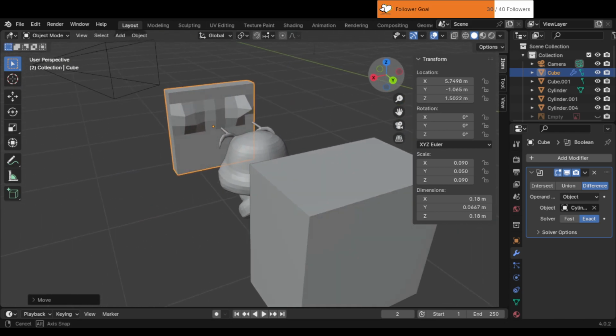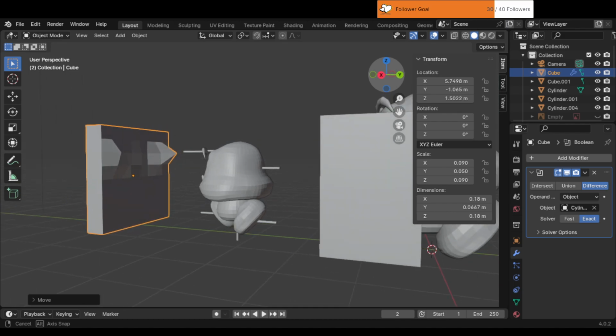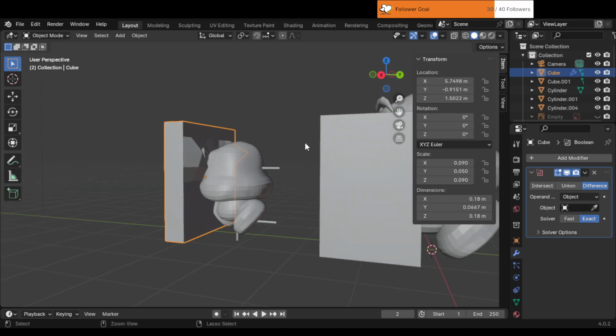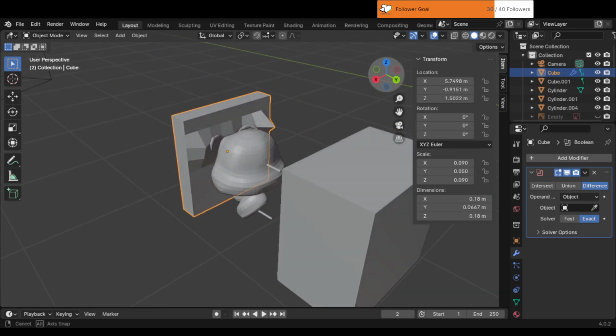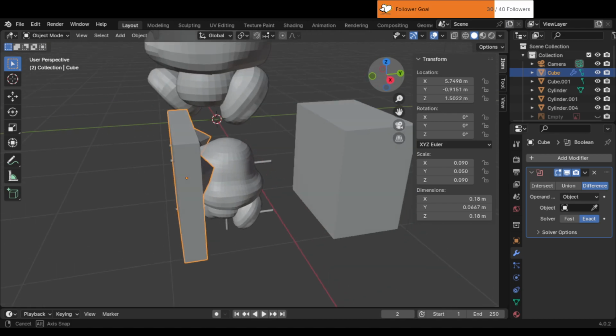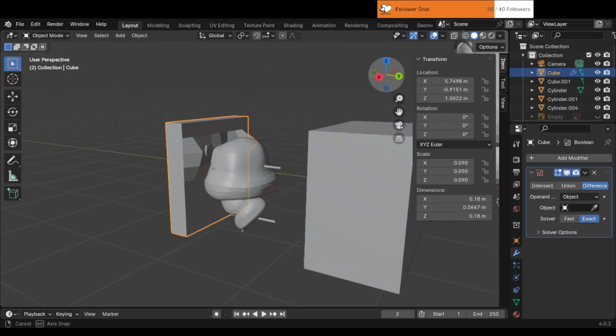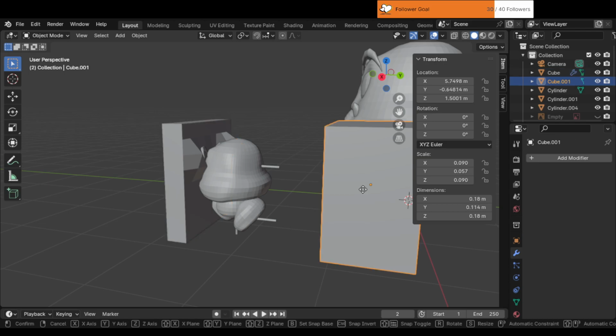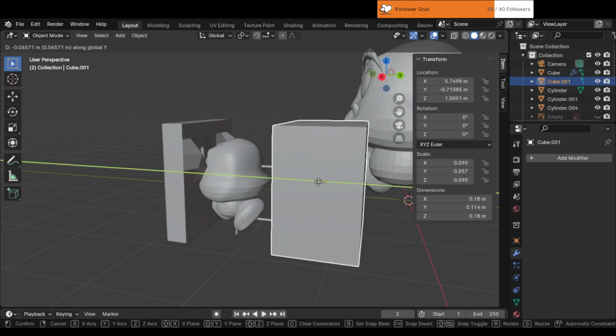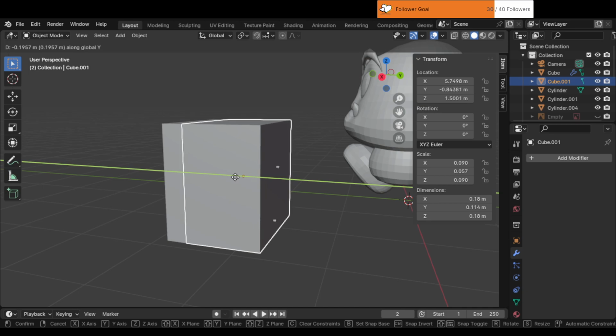Check mesh. Inspect the resulting mesh for any irregularities or artifacts from the Boolean operation. Edit. Use mesh editing tools, e.g., knife, sculpting, to clean up any rough edges or unwanted geometry. 6. Export the mold. Prepare for 3D printing. Ensure your mold is ready for 3D printing by checking the mesh for manifoldness and any other errors.